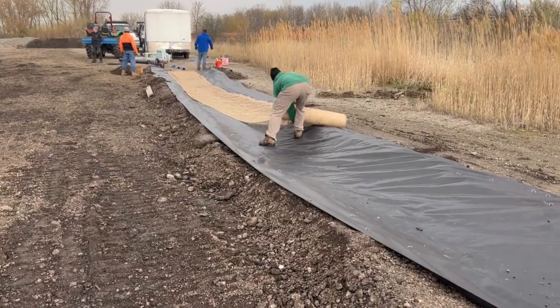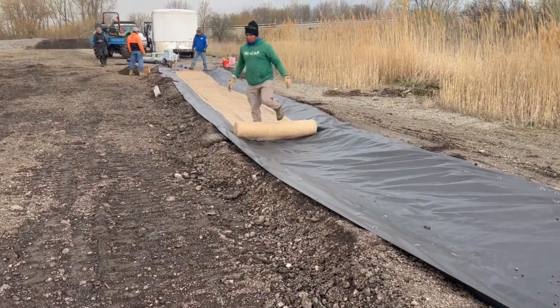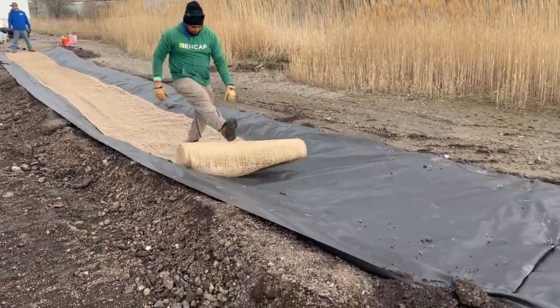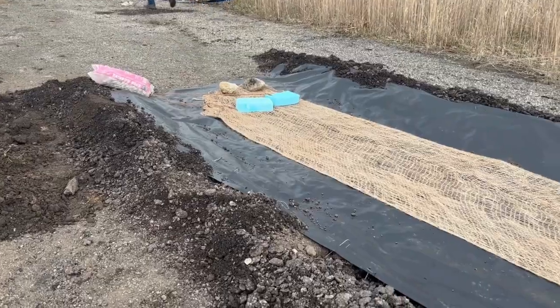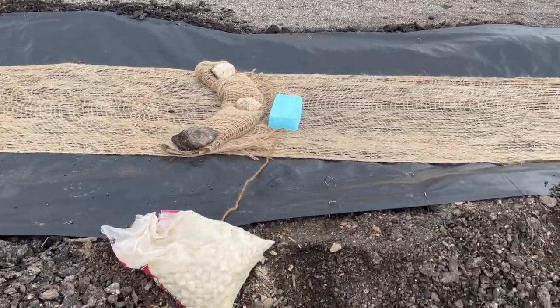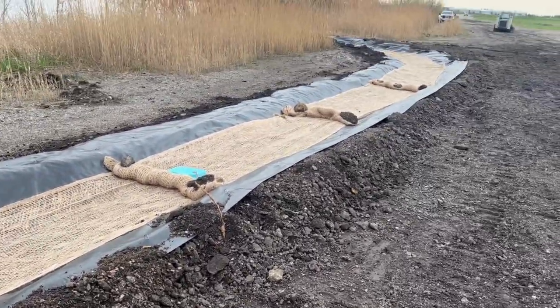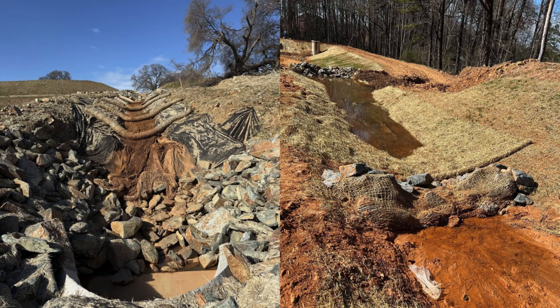Non-chemical BMPs like channel linings, natural fiber matting, and well-placed check dams improve performance by slowing the flow and increasing contact time between the chemical and the suspended solids. These BMPs also help prevent channel erosion, which can reintroduce sediment and reduce treatment efficiency.